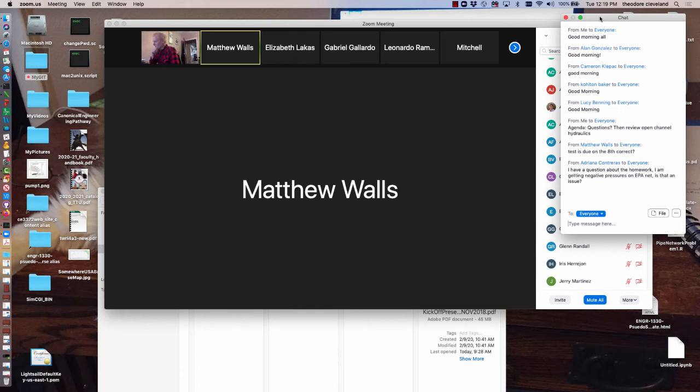The usual solution to that is to check that you've entered the node elevations on every node correctly and that your supply reservoir has enough operating head to produce positive pressures. And it's okay to go to the supply reservoir and put some large value of head in it just to alleviate the negative pressures. If that does it, then it's usually an elevation conceptualization error.